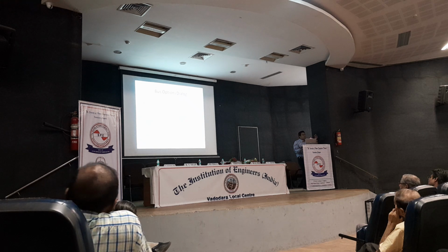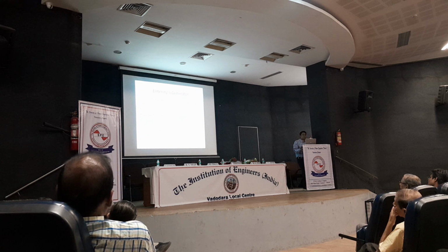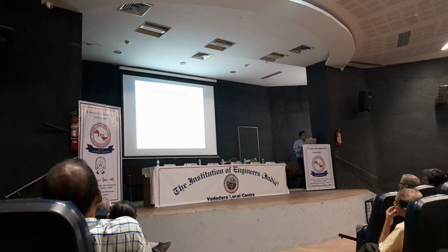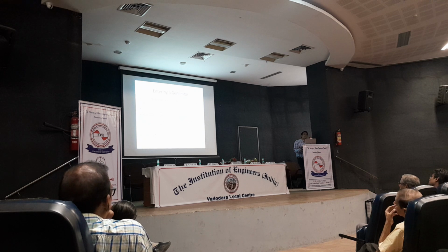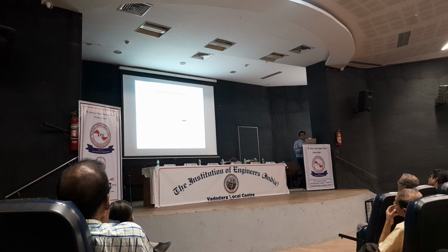So first, by default, we have to select a bus, then we are going to connect a generator to it. In a similar way, we go to the edit mode in Draw. From the Draw option, we select a generator and we are going to set the generator data. If you see the dialog box of this generator, you will find that you have to enter this many